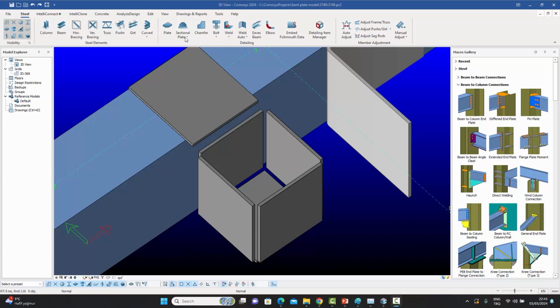What you do is you go here. Like I said, you use the cylindrical bent plate command, and you click on it, and then it allows you to choose either two plates or one existing bent plate and another plate. So I'm going to choose this plate and this plate, and immediately it joins them together. And now this is no longer a normal plate, but this is a bent plate. I can continue by selecting this bent plate and this plate, and it joins those two together as well. You can see from there,